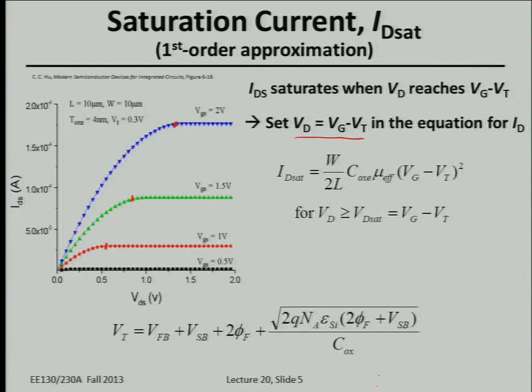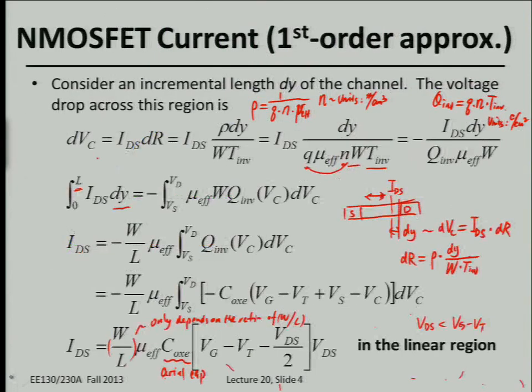You can get the expression for the saturation region drive current. Okay. So it turns out that the drive current is also proportional to the aspect ratio of your channel width versus your channel length. But in terms of the dependence on the gate overdrive or gate voltage, you see a linear dependence at a lower VDS bias, right?